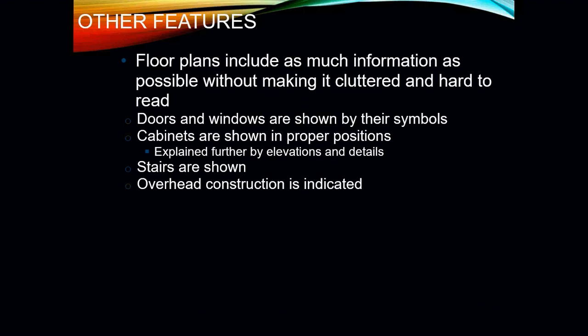Floor plans include as much information as possible without making it obviously cluttered and hard to read. And again, like I said before, every floor of a building or a home is going to have its own separate floor plan. And then depending on how rooms are, even that particular room will have its own floor plan depending on what's actually happening. So doors and windows are always shown by their symbols. Your cabinets are shown in proper positions, which is obviously going to be explained a little bit further by your elevations and your detail plans.